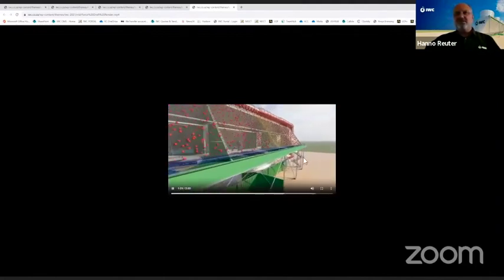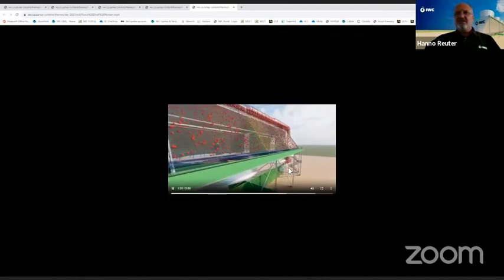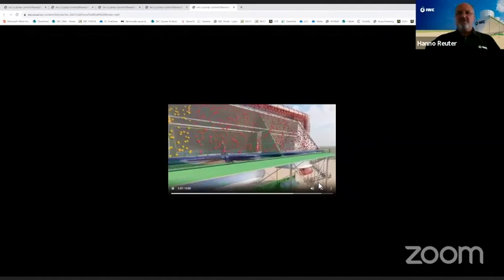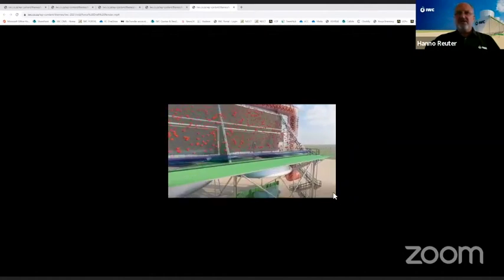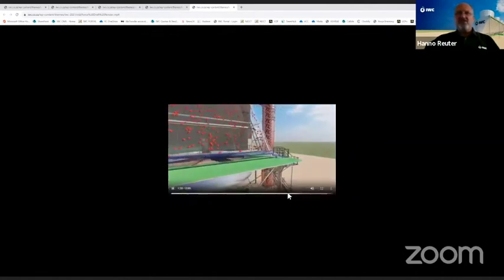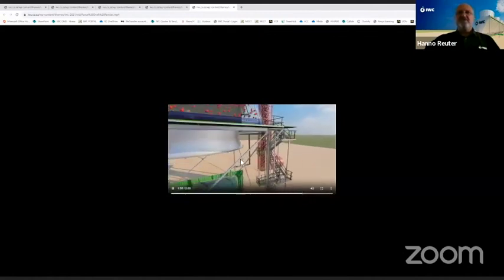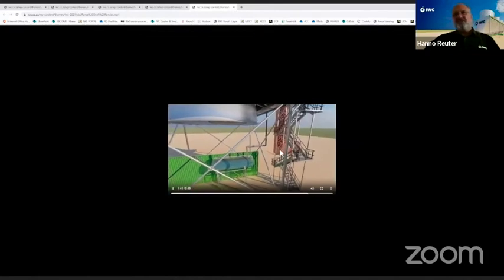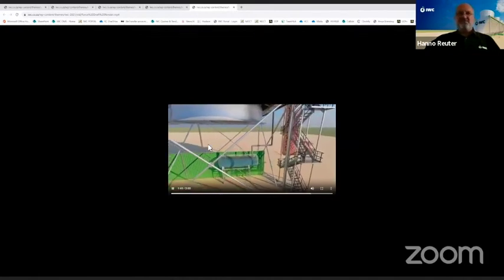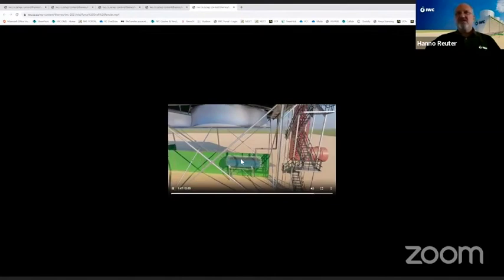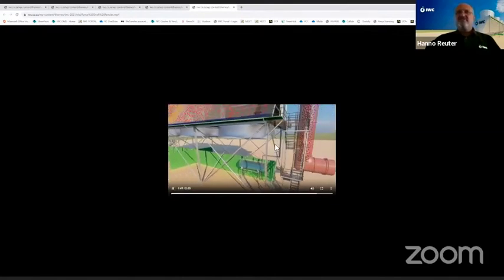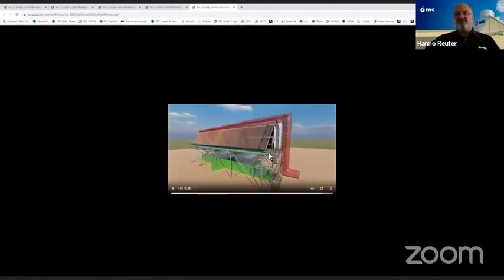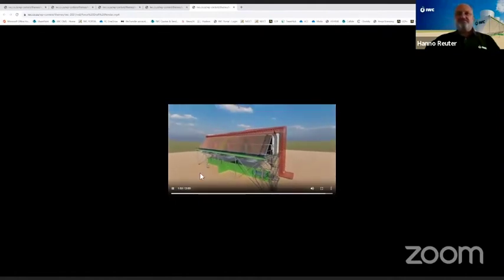So this liquid water then drains into this condensate tank at the bottom here. And this is a forced draft arrangement. So the air is blown in from the bottom. The fan is below the heat exchangers, so it blows the air through the bundles. And this is the technology that's been used up to recent times, I think up to about 10 years ago. And it's often preferred due to the track record and the fact that many references exist on this technology.